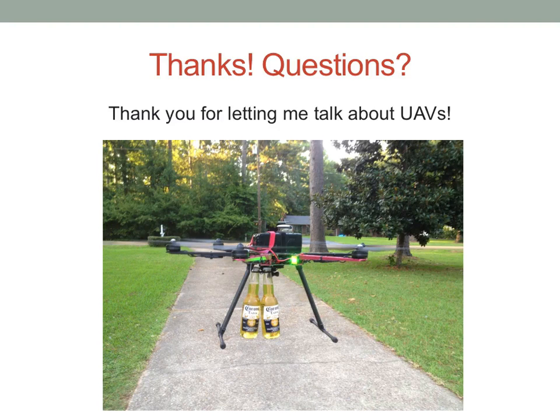But that technology on this new drone is, so it's using sonar like a bat to get a range from the ground, and then it's got a camera on the bottom, not its payload camera, but a small camera that uses computer vision and basically looks for the lines in the tile or anything that's on the ground, a spot. And then as the drone moves, that spot's going to move in that image, and it knows that it's moved, and then it corrects to put that spot back in line with where it's supposed to be on its initial fix. So it's using those technologies.